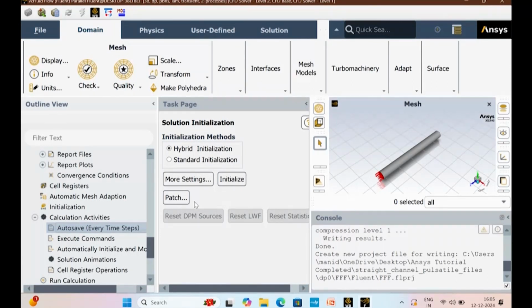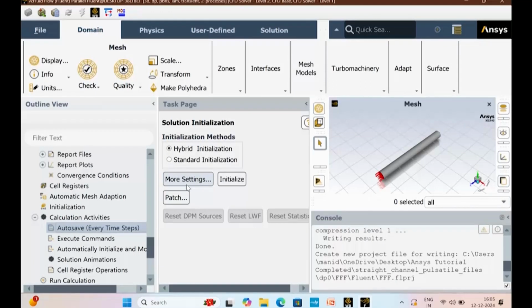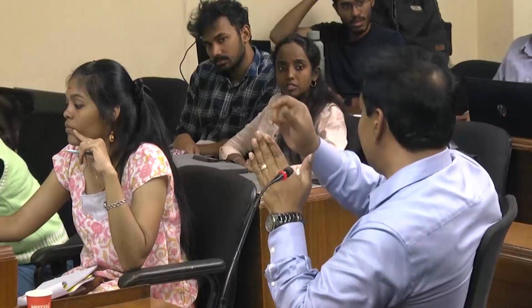So it's actually better to save every time step, but every time step is so difficult because it's huge space. Yes, you have to give a lot of space, and also your simulation will slow down a lot because it will save and take some time. So just do some calculation before you do that. See what your total time is, and what your time step size is, and then you can calculate after how many time steps you want to save the data. Save more, not a problem.